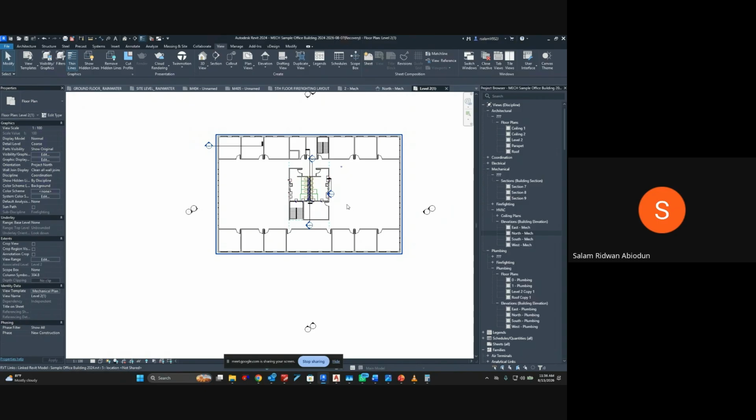Because you don't want to do something, okay, let's say you are proposing a panel light of, let's say, 1200 by 600, and the ceiling is, let's say, a POP ceiling, or what ceiling, or there's not even a ceiling, it's just a slab. It's just an open slab. Do you understand? There's no suspended ceiling. You are proposing 1,200 by 600 recessed panel light. It's not going to work. So you have to change your lighting to a surface mounted. So had you worked with your architect, asking for the reflected ceiling plan, you've checked it, you wouldn't have had that issue. Do you understand?